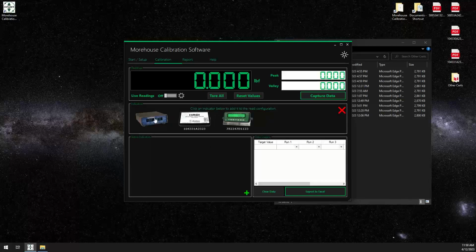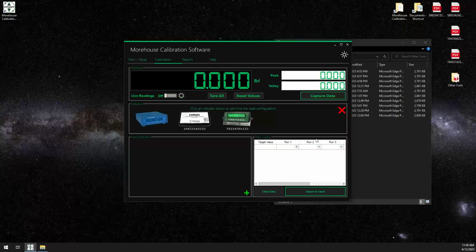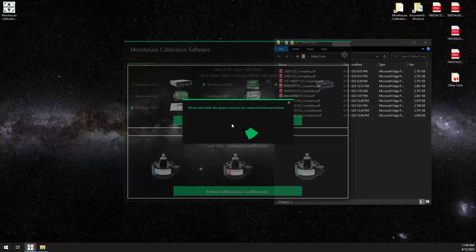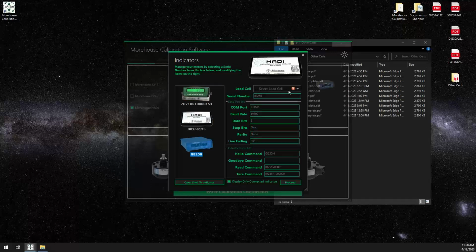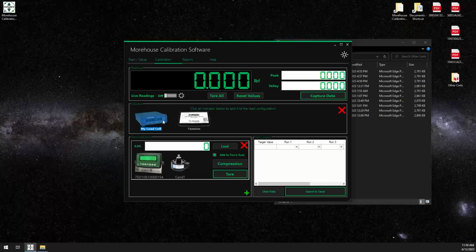It's the default value. As you can see, the interface does not have a value written underneath of it like these ones do. It lets me know, hey, I do not have a load cell selected there, so I need to set something if I want to use it. We're just going to go back here real quick. Change this one to tension, and we'll put our standard on there. Now you see they all have names. Everything is configured to get readings now.